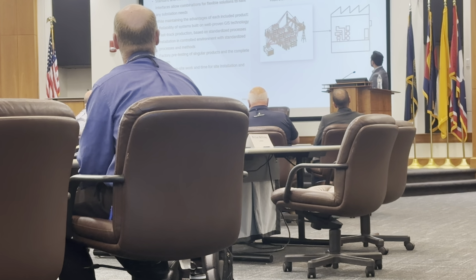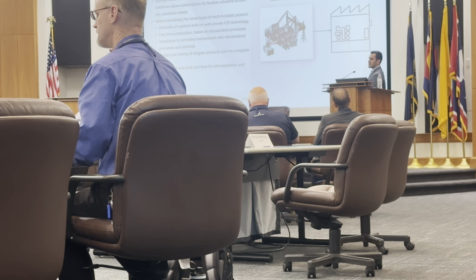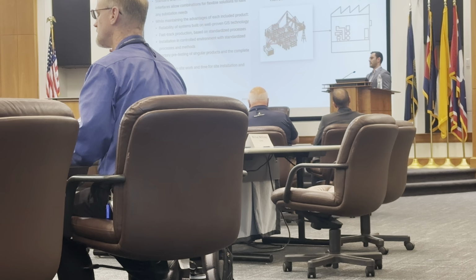With this scenario, you're also looking at pre-factory testing of single products in the complete system, and you're also looking at a reduced on-site installation and commissioning timeline. So instead of having to wait for every single piece of equipment to arrive at different delivery times, in the GIS you're expecting everything to arrive at the same time.